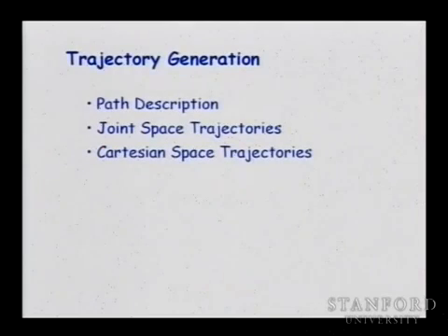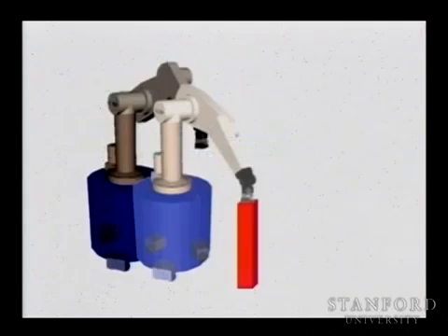And then using those solutions, we can do this interpolation between where the robot is at a given point, and how to move the robot to the final configuration through trajectories that are smooth both in velocity and acceleration, and other constraints that we might impose through the generation of trajectories both in joint space and in Cartesian space.